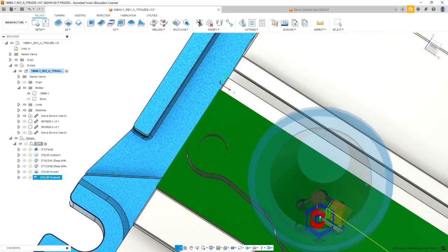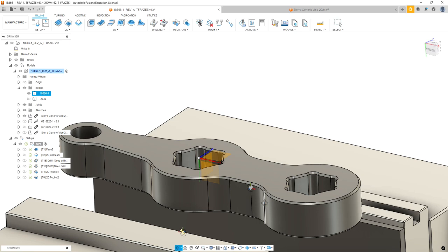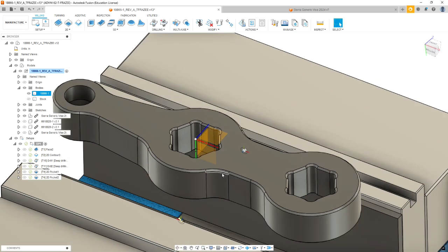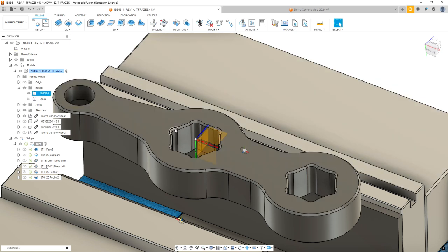Chamfers, the bane of existence. Now we're going to do our chamfer milling. I have been using Fusion for quite a while, and I've always picked the bottom of the chamfer edge when it's modeled. Never had any problems until I regenerated this, and now it doesn't work. So let's go through this. Hopefully this works. The fact that these were pre-drilled might be an issue. It may not be seeing material to remove there.